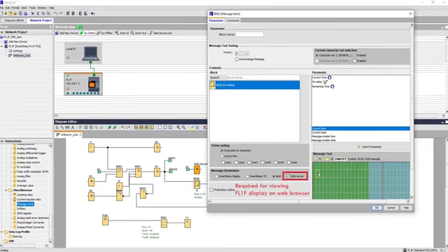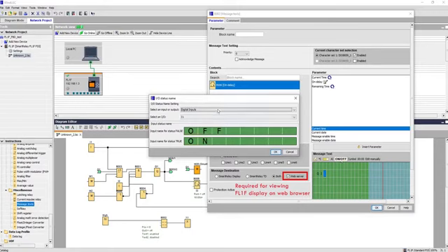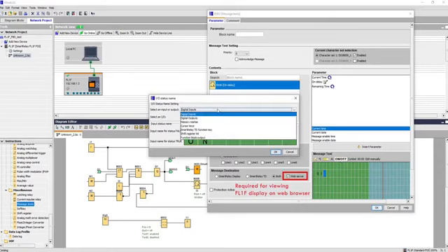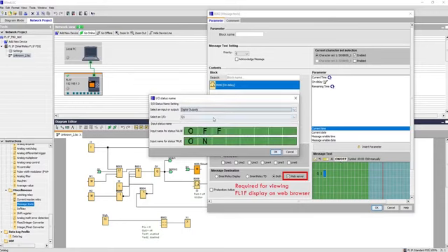We'll go from scratch. I'm entering Q. I've entered Q with the help of the keyboard. Then Q1 is the output. Whether we would like to check if it's on and off, just click on and off here. It will ask what exactly we would like to monitor here, digital outputs, and the output number is Q1. The status, how it should show, is mentioned over here.